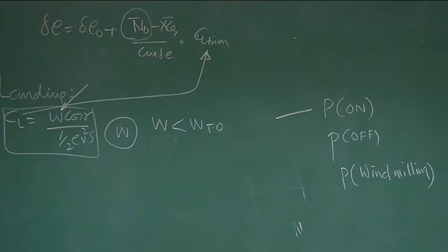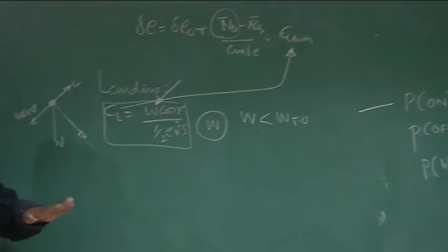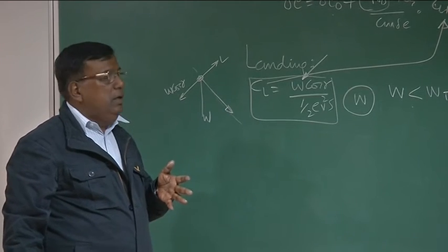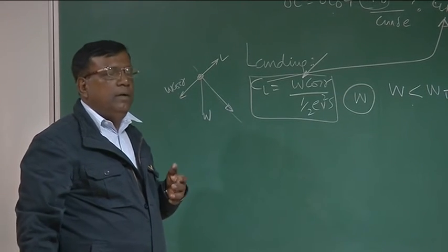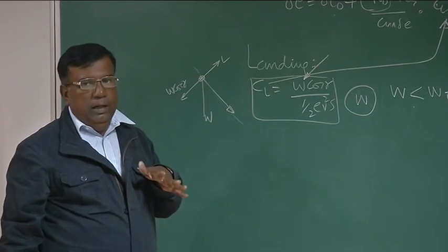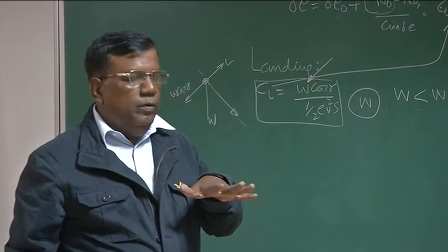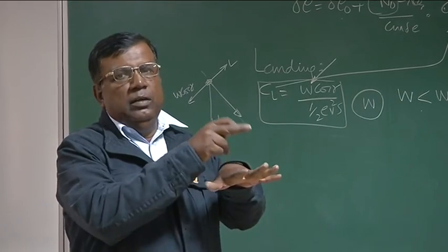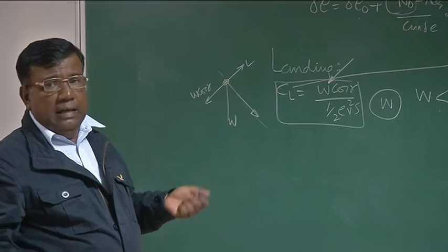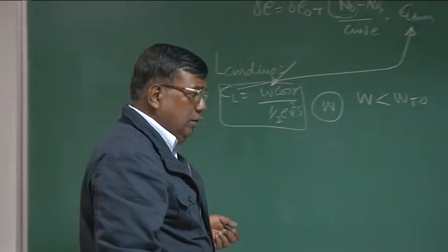Which one should I pick? Generally, when I'm landing like this, ideally the power should be 0, because why do you want unnecessary power? But that's not the case for all safety arrangements. So the propellers are generally put in a windmilling condition. That is, when it's moving, it is also rotating because of the windmilling effect. And sometimes the pilot will set 10-20% power.